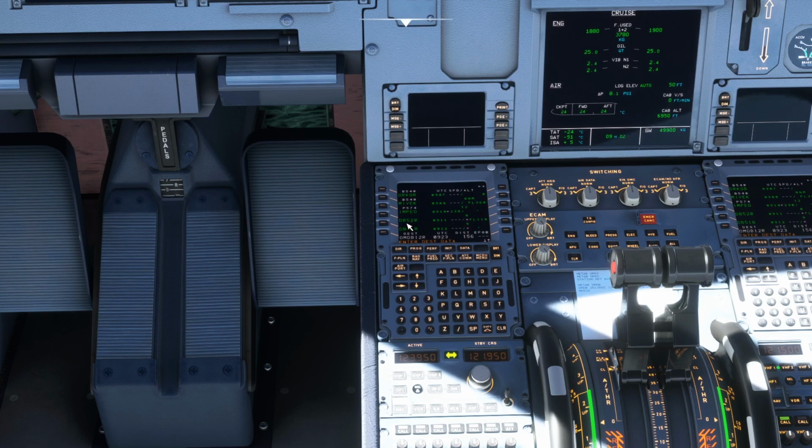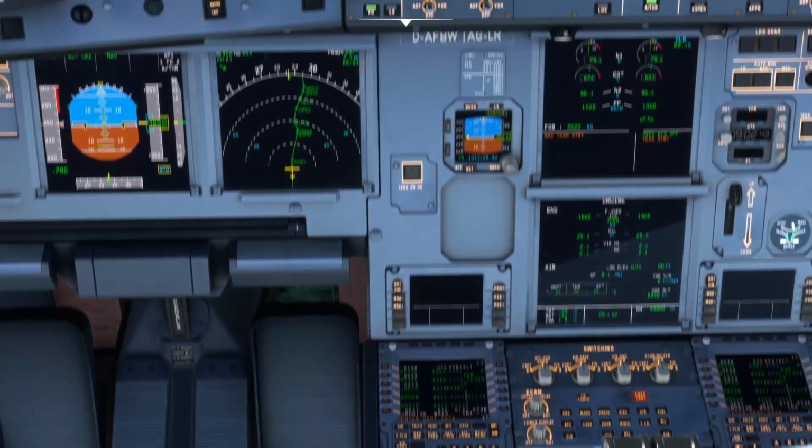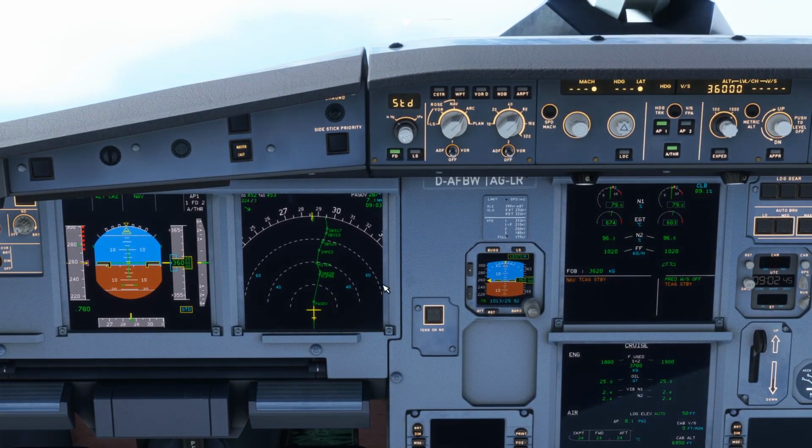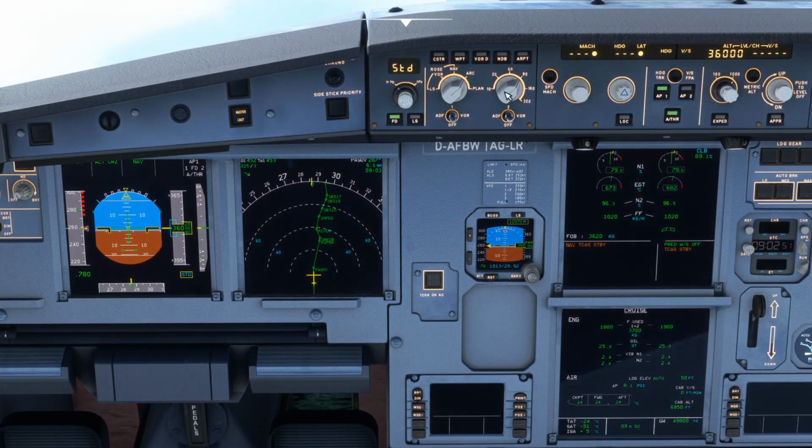And at DB 520 you should be at flight level 110, that's 11,000 feet. So this can give you a good idea that after MIVEK you have to start your descent. You can descend to flight level 110. If I look at the screen, this is MIVEK, and the next waypoint is DB 520. Can we see 520? No, we cannot.